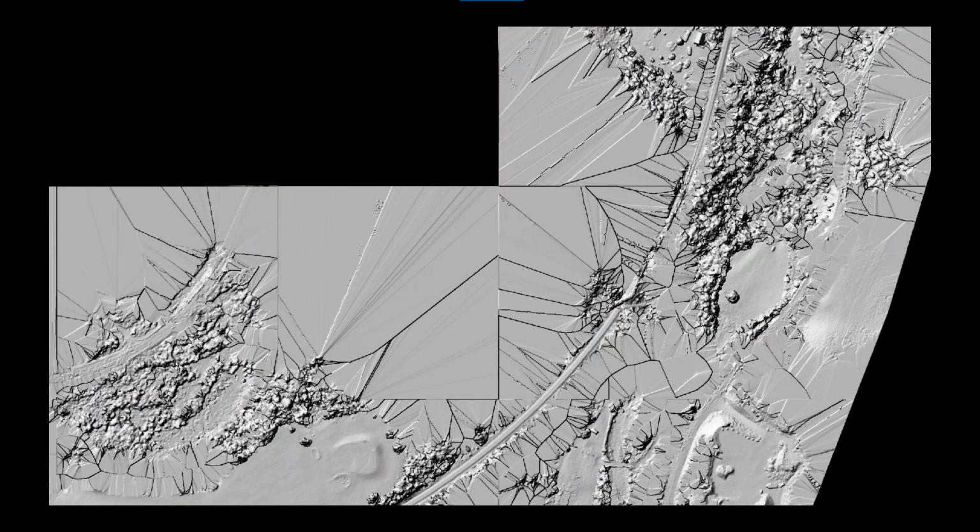Okay, meaning that because of the trees and their condition at the time, we weren't able to get good ortho photos. And if we move over to the digital surface model, which you see in this next slide, that also gives us a very good indication. You see that interpolation, those triangulated areas where we didn't have good matching between the photos.